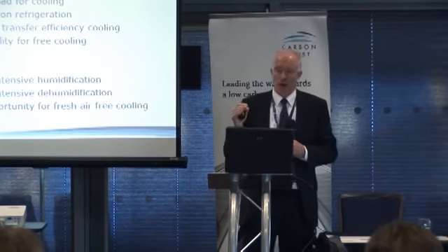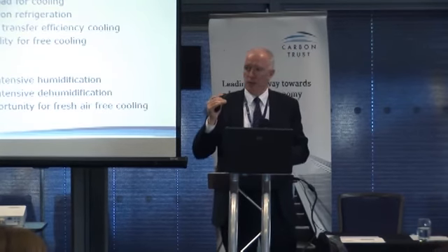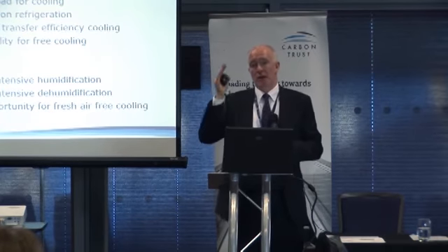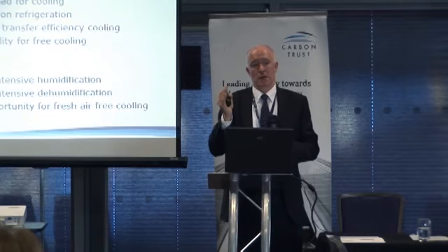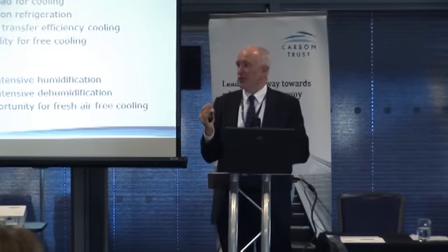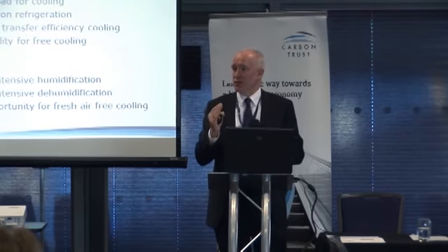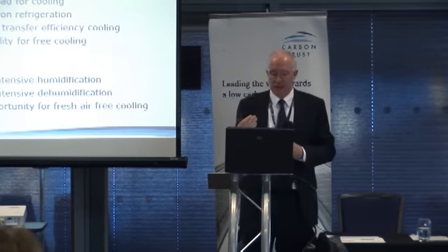As you raise the temperature of the room, the difference in temperature between the evaporator, the cooling point on your refrigeration, and the air becomes greater. That again improves the heat transfer efficiency, or we can float the temperature on the evaporator, but it improves the heat transfer efficiency, and therefore again you'll get efficiency gains there.